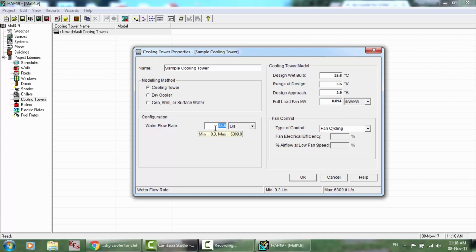cooling tower, but this is not easy as an initial designer. For the initial design, you may not know the total flow rate of the cooling tower. So it's recommended to use the difference here, and here are the minimum and maximum that are available. This is the delta T of the entering water of the cooling tower and the water that exits from the cooling tower. Okay.